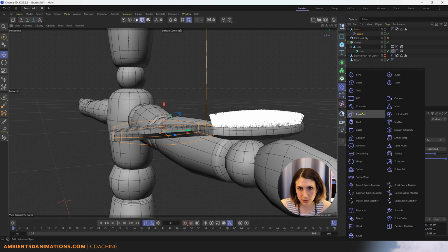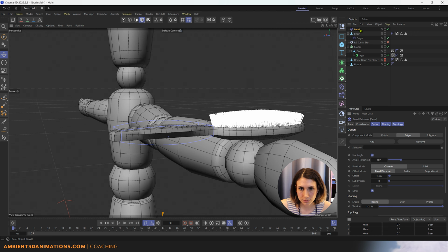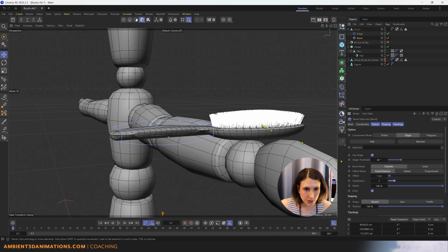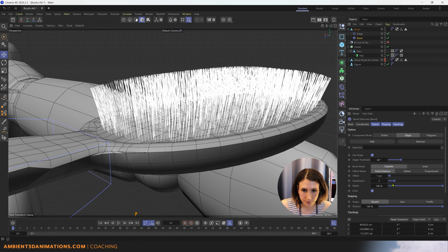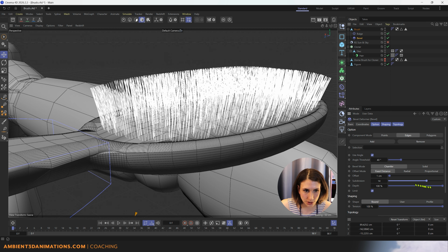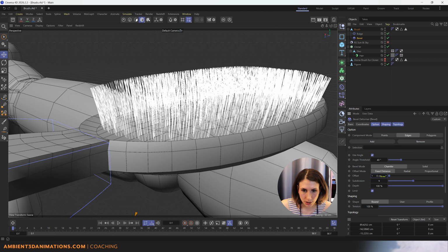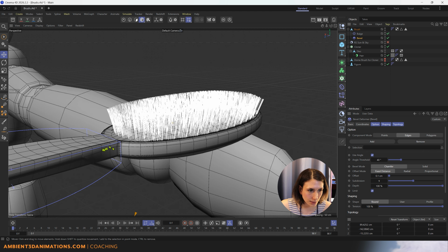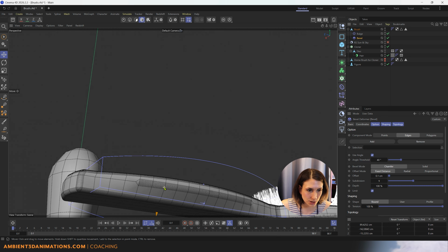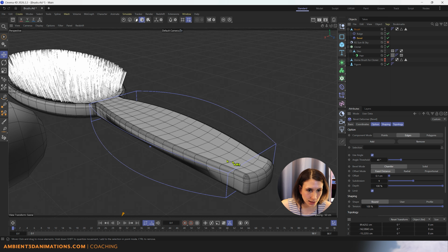So you'll see we have something called the bevel deformer in here. I'm going to put this right in here. And I'm going to increase the number of subdivisions. So you can see that what this is doing is it's adding bevels along here, little curvature along the edges, and you can increase the number of subdivisions. You can choose the radius right now of that bevel. So I can make it something pretty small, like 0.1, and you'll see that it just smooths out some areas in here.